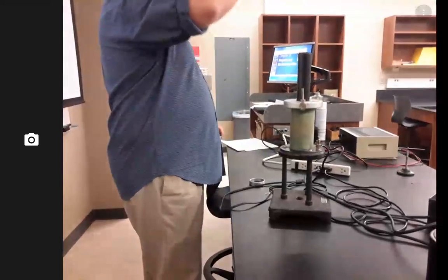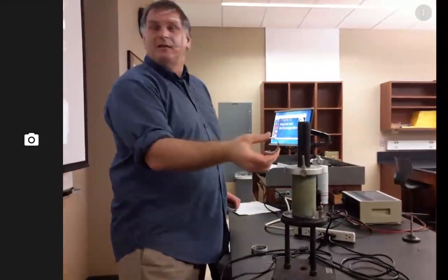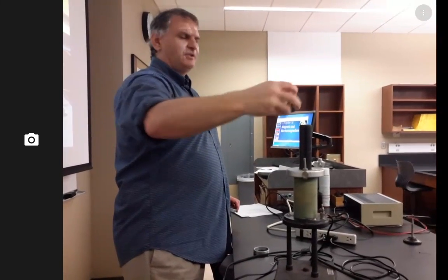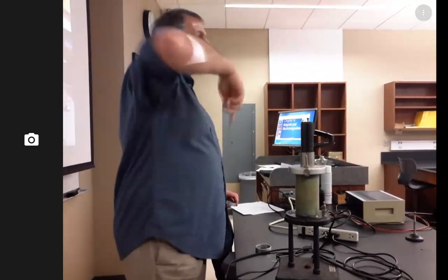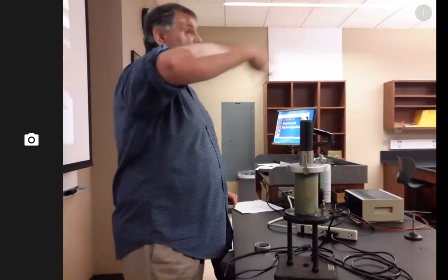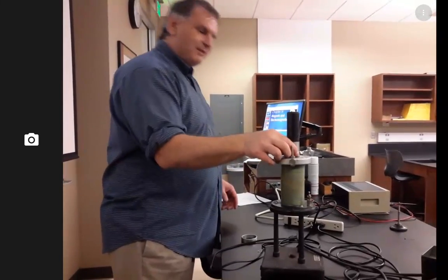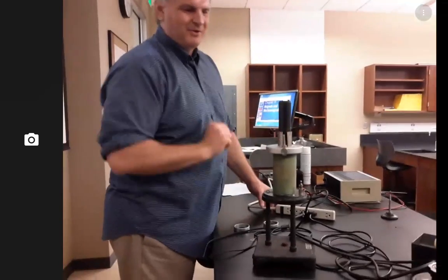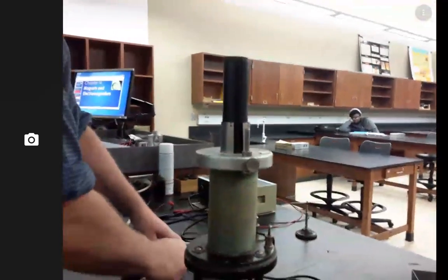This here. What's different? It's aluminum. It's thin aluminum. Who cares that it's thin? What's different is it has the hole in it. So if it has a hole in it, you can't have current going around the loop because the loop's broken. You don't have a complete circuit. So let's see if that makes a difference. Okay, I'm going to rotate this so my videographer can see the gap there. And plug it in. Nothing.